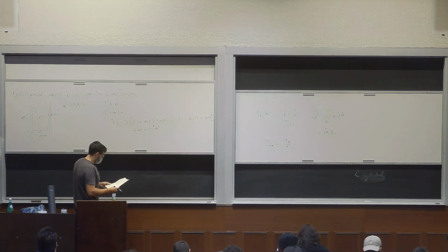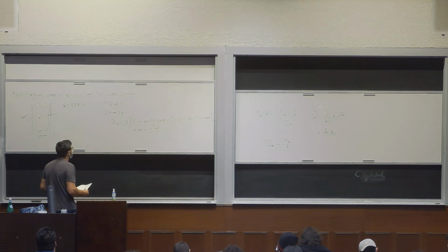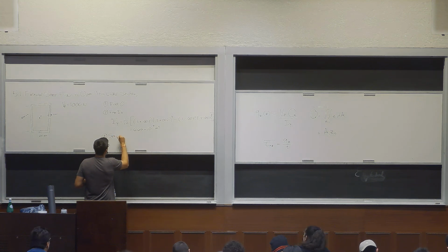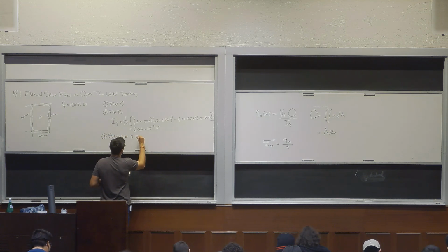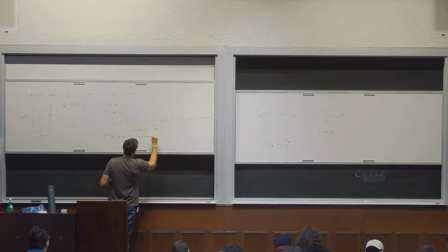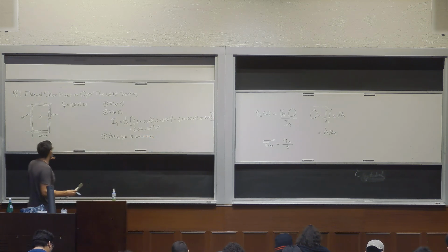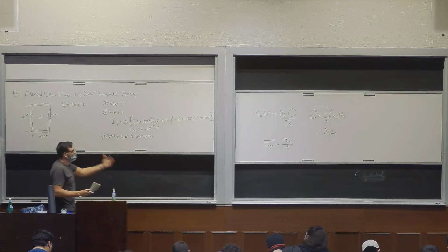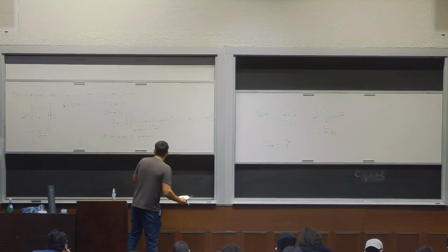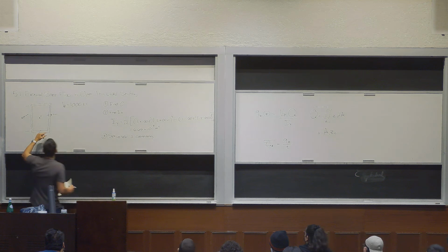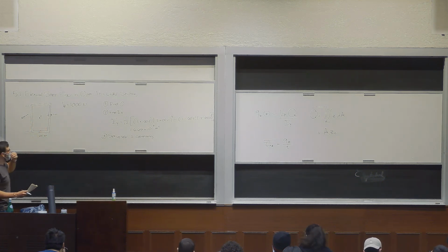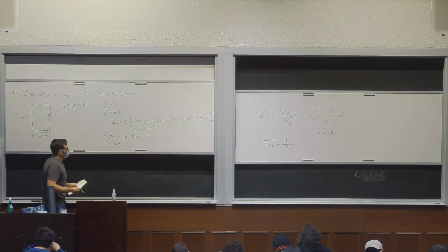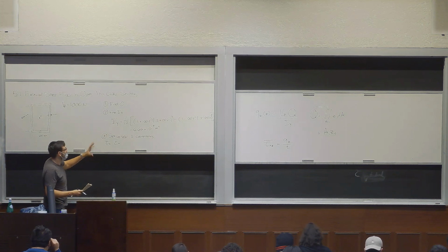The third step is where things start getting interesting. Step 3 is set up the coordinates, your S coordinates. Okay, so for problems from now on, in these thin-walled sections and the spar web sections, we're no longer dealing with tau xz or tau xy because the coordinate system may not align exactly with the direction of the shears. So we're going to be dealing now with tau s and tau n, mostly tau s. Okay, what are s and n?